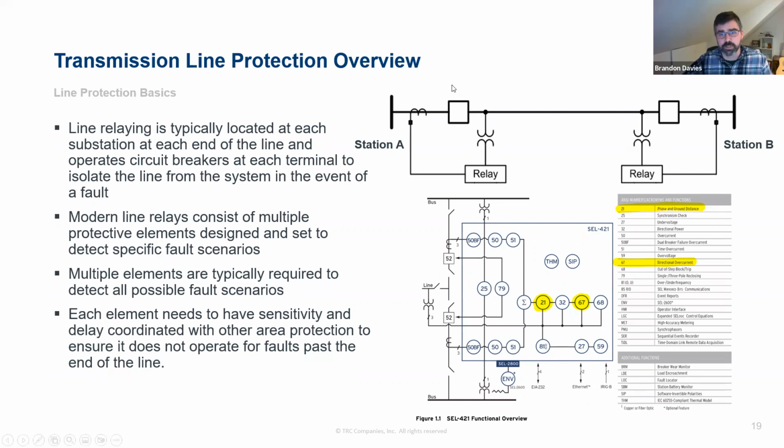So there's a specialized scheme. It's more of a logical scheme that someone developed. It's been around for a long time, and it's been used pretty regularly for a case where you do have line side connected VTs, because the relay could also be measuring bus voltage, since there's really not an electrical difference between those voltages. It's called switch on to fault.